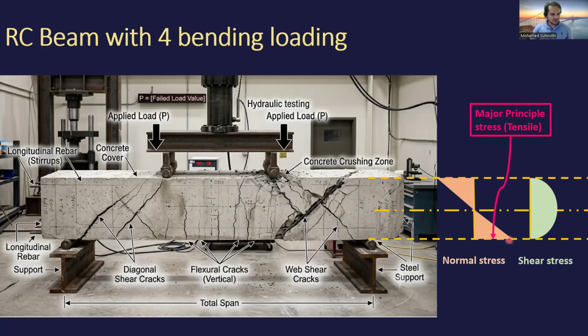So how will the normal stress act? It will act this way, in the horizontal direction, right? Okay, normal stress acts this way. So that means perpendicular to this normal stress would be your crack orientation, right? That's what you see. The crack here is vertical, right?